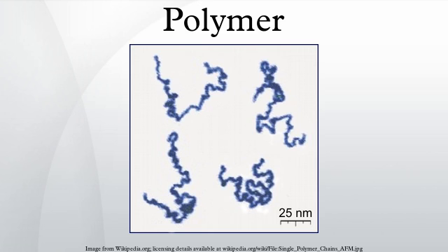Microstructure. The microstructure of a polymer relates to the physical arrangement of monomer residues along the backbone of the chain. These are the elements of polymer structure that require the breaking of a covalent bond in order to change. Structure has a strong influence on the other properties of a polymer. For example, two samples of natural rubber may exhibit different durability, even though their molecules comprise the same monomers.